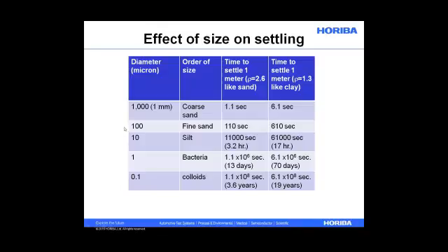As I move my diameter down to 100 microns, which is like fine sand, well, now we're looking at 100 to 600 seconds. So that's about 10 minutes. Doesn't sound too awful yet. 10 micron, which is about the size of silt. Well, now it's 3 hours if it's something as dense as sand, or 17 hours if it's something like clay.